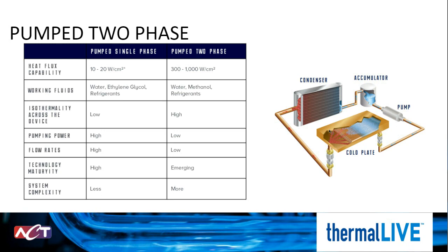The other benefit of pumped two-phase is the size. In single-phase designs, higher amounts of heat are removed by increasing the flow rate of the fluid, which requires a larger pump. But with pumped two-phase, the system is designed to interact with the component on a saturation level, or essentially it's designed with a pressure that will vaporize at the desired component temperature. Because we are not increasing the temperature, we're able to remove higher amounts of heat. This gives us higher temperature control without needing a large pump.